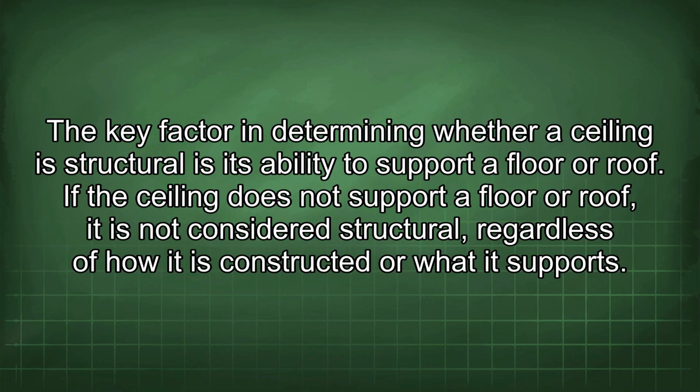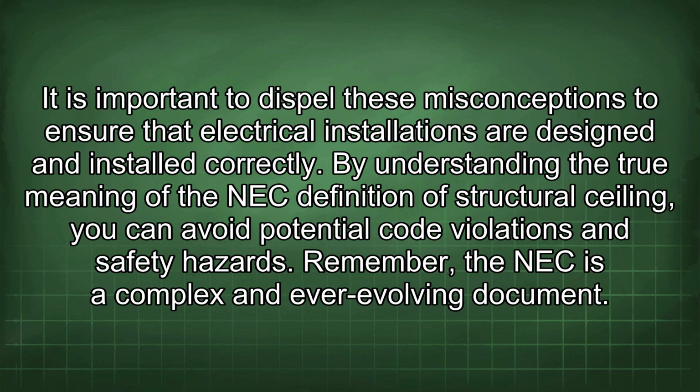The key factor in determining whether a ceiling is structural is its ability to support a floor or roof. If the ceiling does not support a floor or roof, it is not considered structural, regardless of how it is constructed or what it supports. It is important to dispel these misconceptions to ensure that electrical installations are designed and installed correctly. By understanding the true meaning of the NEC definition of structural ceiling, you can avoid potential code violations and safety